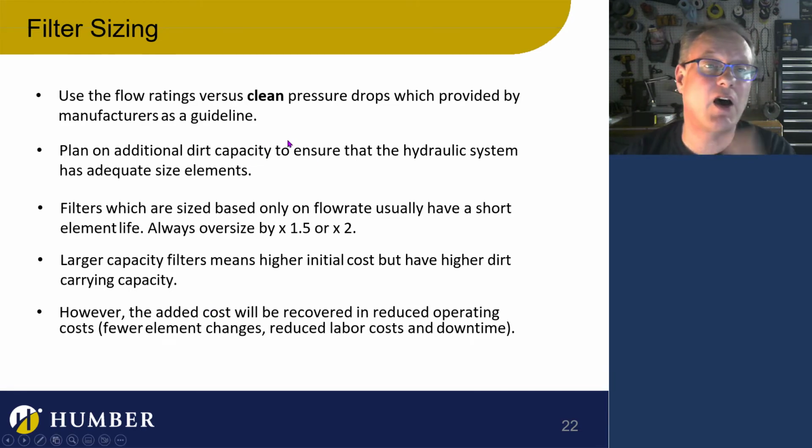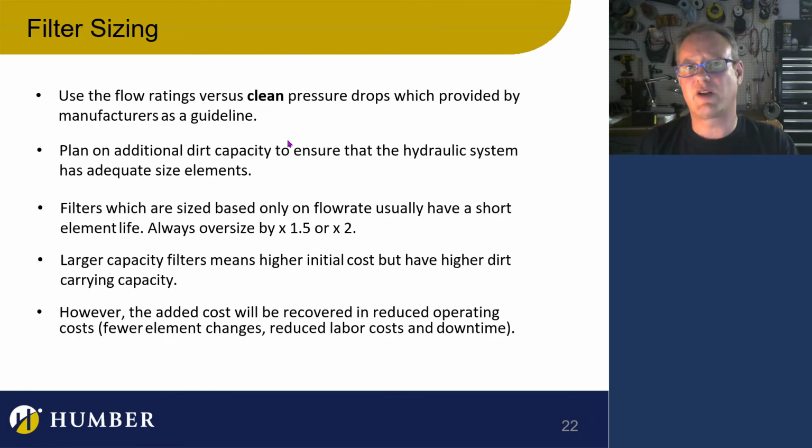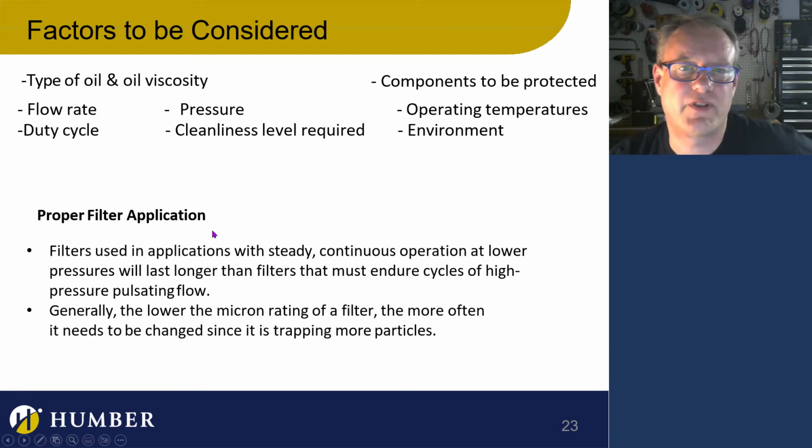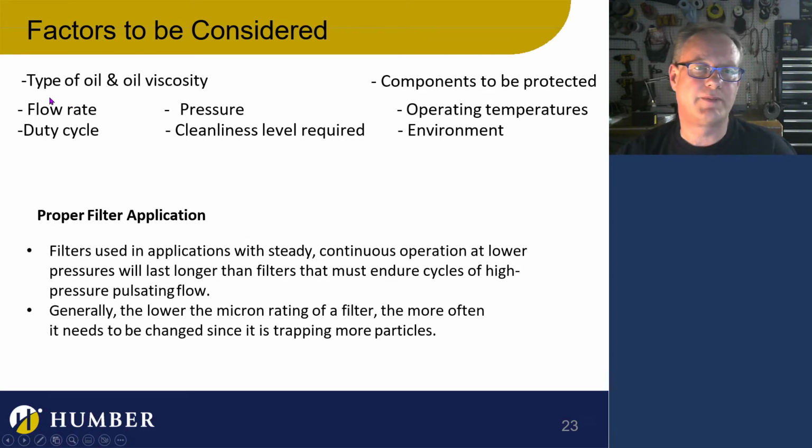But there's the ease of filter sizing, also the type of filter that you're going to put in, and where it's going to be located in your system. You want to put it as easy access as you can. A spin-on filter is always the best way to go, because it's really easy to change. So filter maintenance is huge. So, factors to be considered: the type of oil, viscosity itself, the flow rate, the duty cycle, pressure, and cleanliness levels required. We're going to talk about cleanliness levels. I'm going to do a few slides on this because it's really important. All of these things are really important that you have to consider when you're selecting the filter.